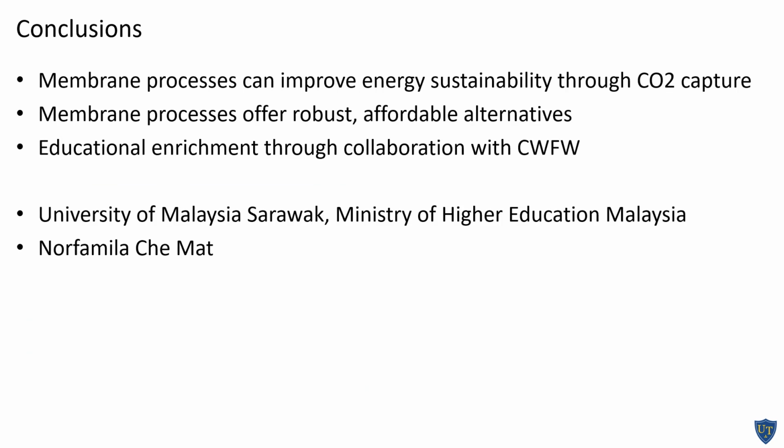And with that, I'd like to draw a few conclusions. First, I believe that membrane processes offer a viable option for CO2 capture. They are robust and affordable alternatives to meeting the DOE targets of 90% capture, production of a CO2 product of 95% purity, and doing so without increasing the levelized cost of electricity by more than 35%. Moreover, they offer unique opportunities for integration, retrofitting of existing power plants.